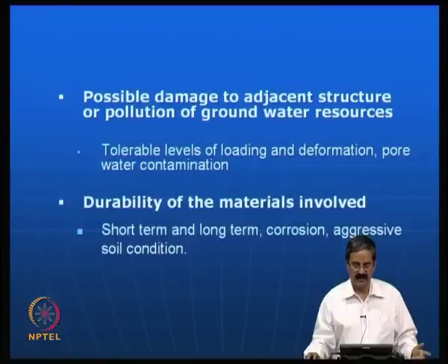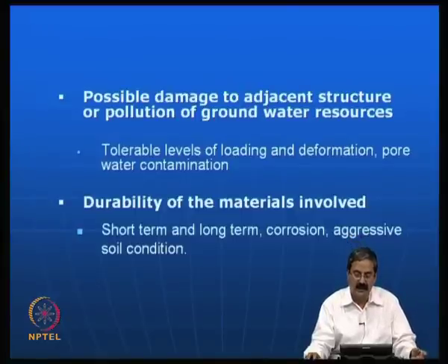If you just remove some amount of soil next to the ground, what happens? Actually, the apartment is standing because of the confinement effect. Now, you removed some overburden of about 5 meters, then all the failure planes develop towards the excavation side and the whole constructed building starts to tilt. That is a very dangerous situation. So, one should use proper ground improvement techniques.